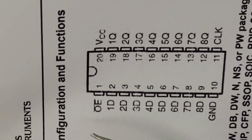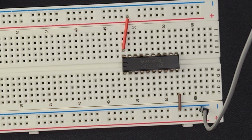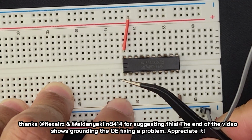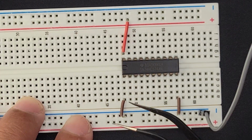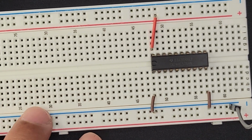VCC and ground, and we can ground the OE as well. So let's do that first. So that's power, ground, and I'm going to ground the output enable because it's inverted. A 0 on the output enable keeps it outputting activated. And now we need to get the 4 inputs, 1, 2, 3, 4, from our instruction pointer because right now we only have 4. Then we need to output to more LEDs.